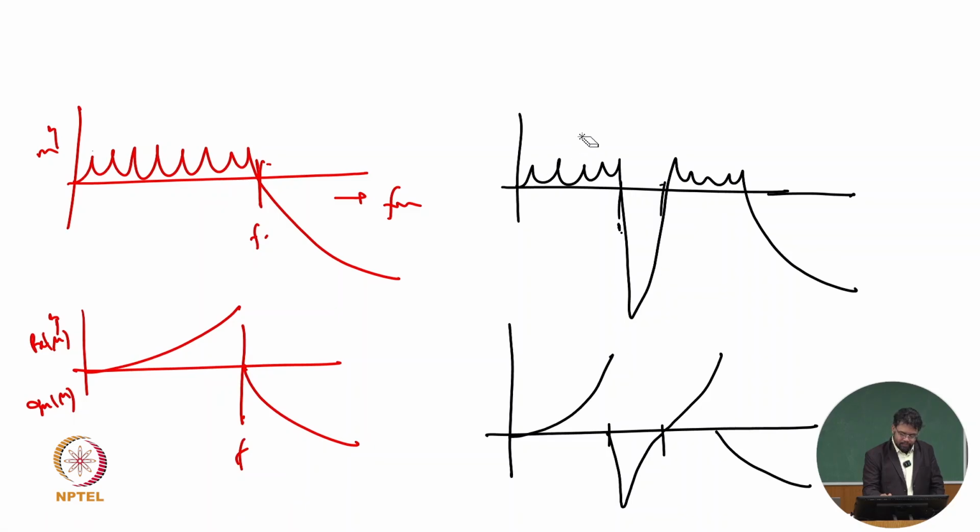So the number of units plays a role, but after a certain number of units you will find that things start converging, and then there is no problem. Generally 6, 7 or maybe 7, 9, after that you will find these things are coming out pretty okay, and you are getting definite portions. There is no standard actually. You can think of it like finite element, where we have to do mesh convergence to find out when the result is converging. Generally we do not go anything less than 5.